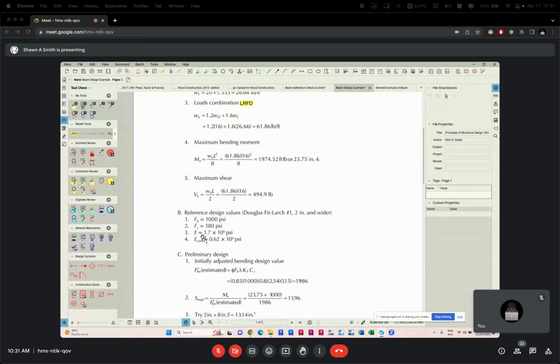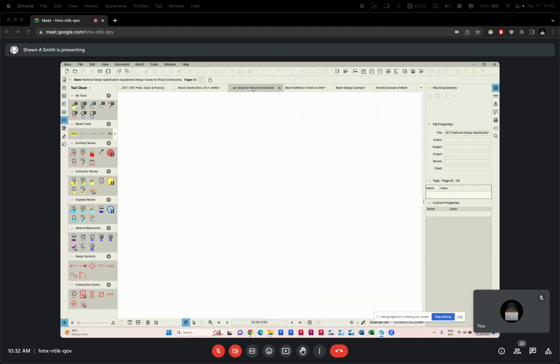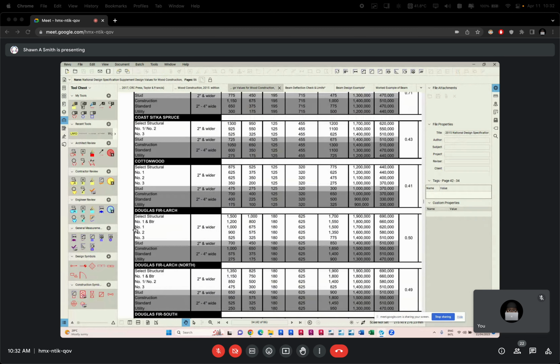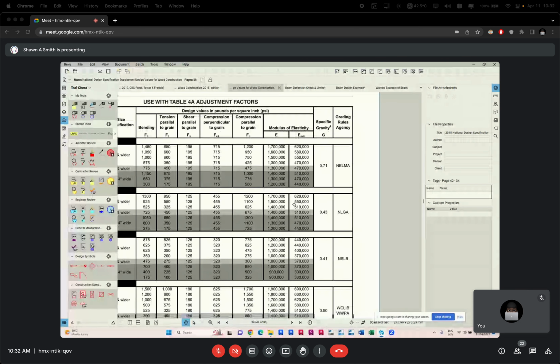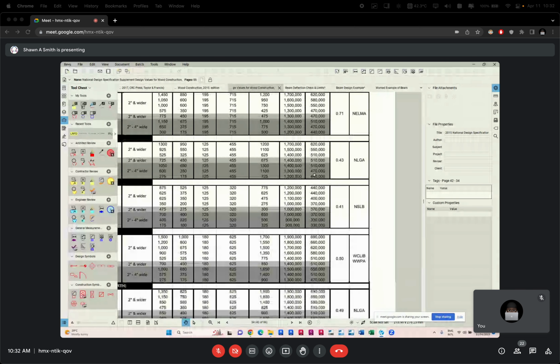And because we're going to check deflection, they take out the modulus of elasticity for deflection, and this also comes in for bending, so we take it out. So we take out both moduli of elasticity, E and E min. So let's go back. For the same element, Douglas fir large, number 1, those E's come as the penultimate, the second to last.